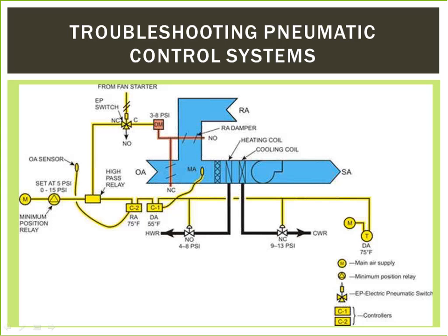Another method is where the air pressure coming from the thermostat feeds an electro-pneumatic switch or transducer. The transducer converts the air signal to an electrical output, which in turn controls an electrical actuator or coil, ultimately controlling temperature.